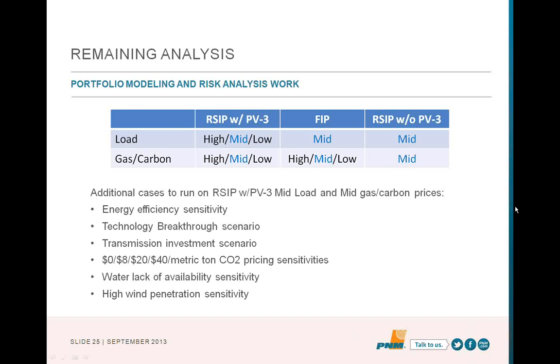And then as we look at what the potential is, I think we'll find most of the wind resources on the east side of the state. For us, we've got one dead-end line that heads out east, so we'll need to look at what the capacity capability is on that line, look at what transmission investments might be required to tap more wind to bring it onto the P&M system. And then we can also broaden it to other things like the SunZia project. There's potential that subscription to that project might achieve the same goal as investing in our line.